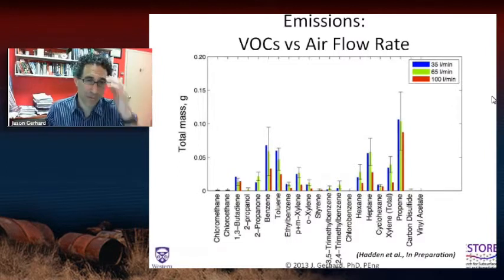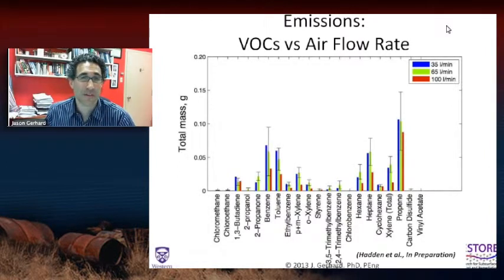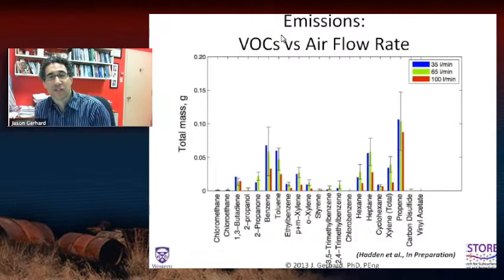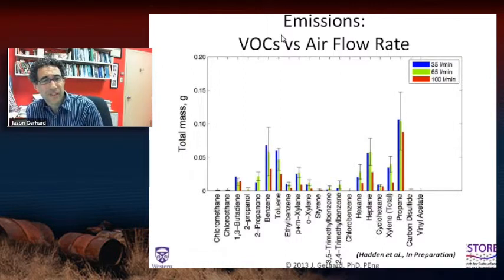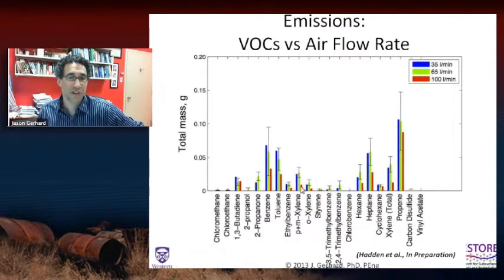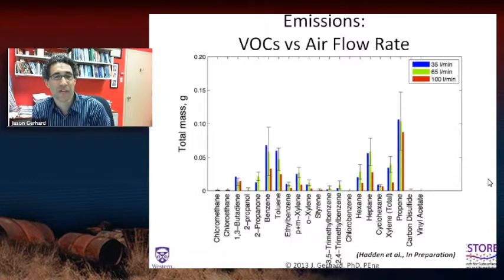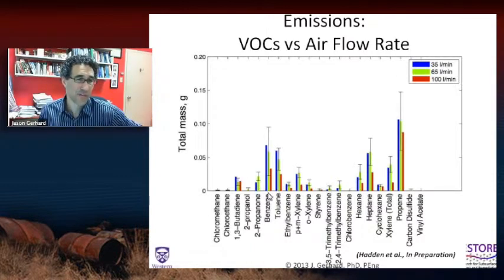And here is one example result, a preliminary result, being written up for a paper right now. Here we're analyzing for total VOCs. This is for an oil sludge. We're quite interested, I'll show you for one of our projects in treating soil contaminated with hydrocarbon, basically crude oil sludge, very heavy crude oil. And what you see here is the range of compounds that are detected from a full suite of VOC analysis. So we're seeing here on the order of 15 compounds out of all 63 that we measured for. And you see some of the typical compounds that you're familiar with: benzene, toluene, the BTEX compounds, heptane, hexane, some unusual ones, for example, propene.